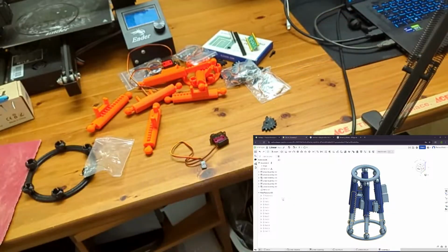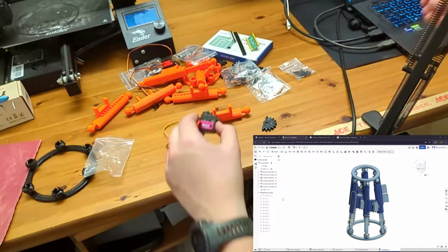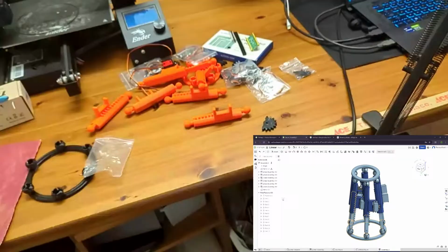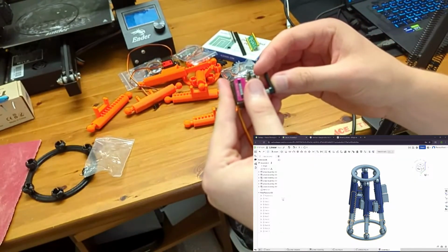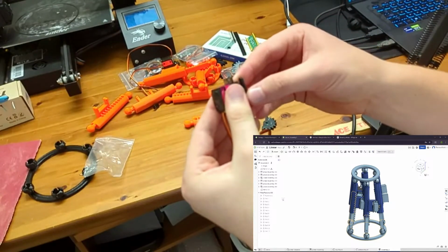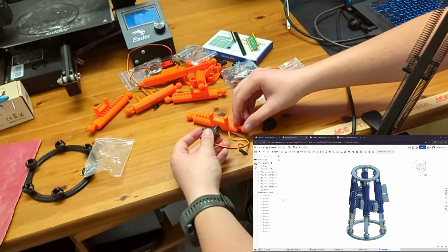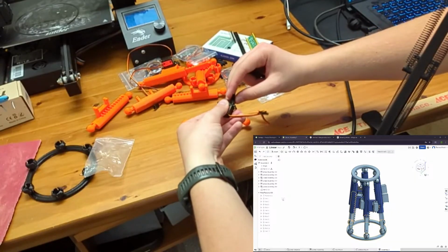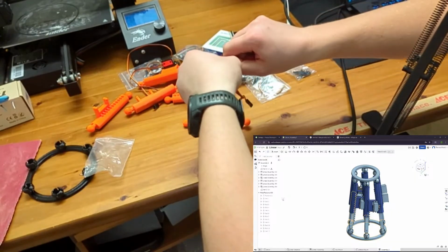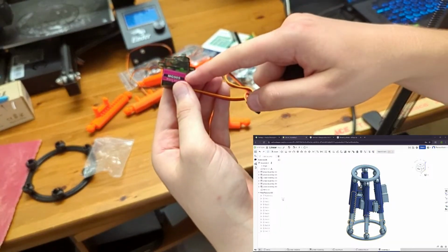Now, one thing I would be doing more ideally is I could have set it up so that I had a servo tester or a microcontroller already ready to go to set the motors to the final position, and that way I could set the gears with the right position corresponding to the potentiometer built into the servo.